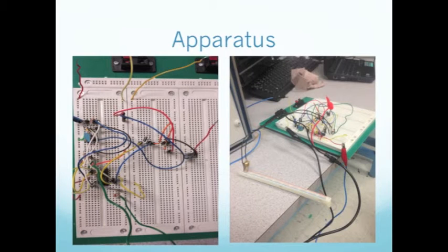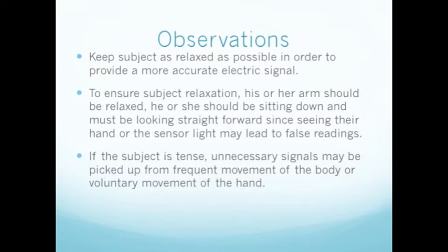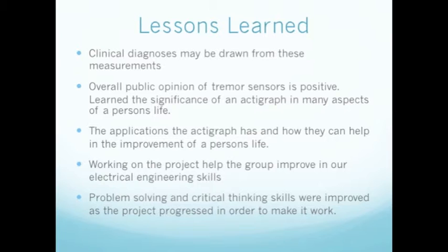The following components were implemented in the lab. The transducer with the patient interface apparatus will now be connected to the input terminals. With no displacement of the transducer, we confirm that the DC voltage at the input to the envelope detector is at the ground potential. We also adjust the potentiometer to adjust this voltage to 0.